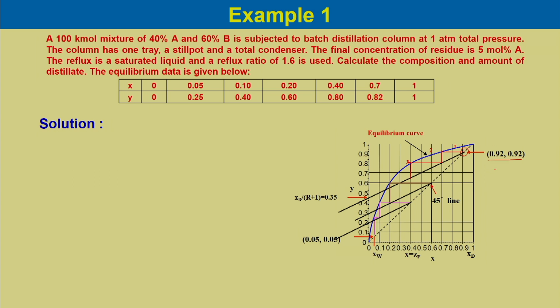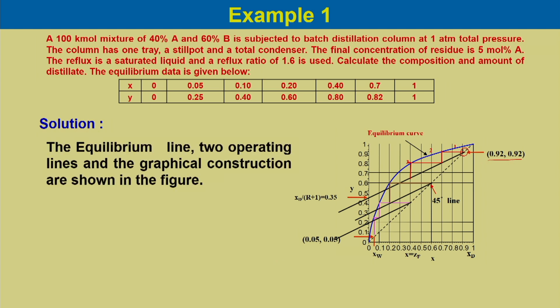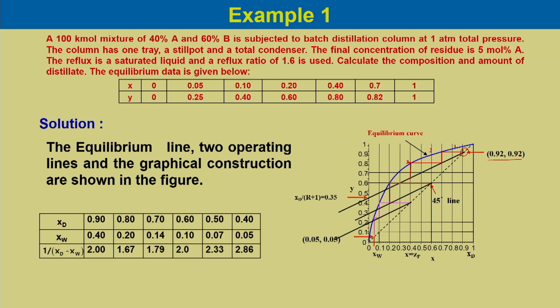It is taken from 0.9292, but actually if you just plot the equilibrium line and then the operating lines, both the stripping section and rectifying section, you need not draw the operating line for both the sections. So, from here with the slope you plot the operating line. Once one operating line is known, the other operating line you can draw from the 45-degree diagonal by drawing parallel lines.